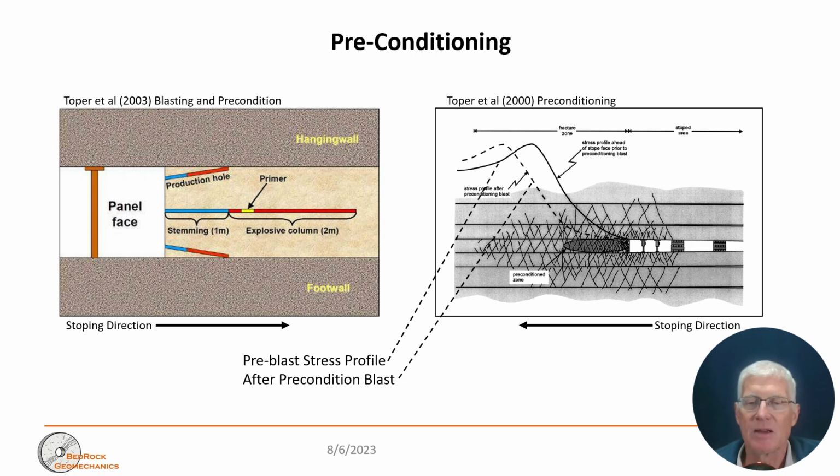It's a little hard to tell if it actually works, but in most cases it is thought to be quite helpful. The other way to do preconditioning is fracking: you pressure up the fluid pressure until it causes new fractures to form in the area where you're going to be mining. That's done particularly in the eastern states in Australia, I believe. So that's another possibility for preconditioning.